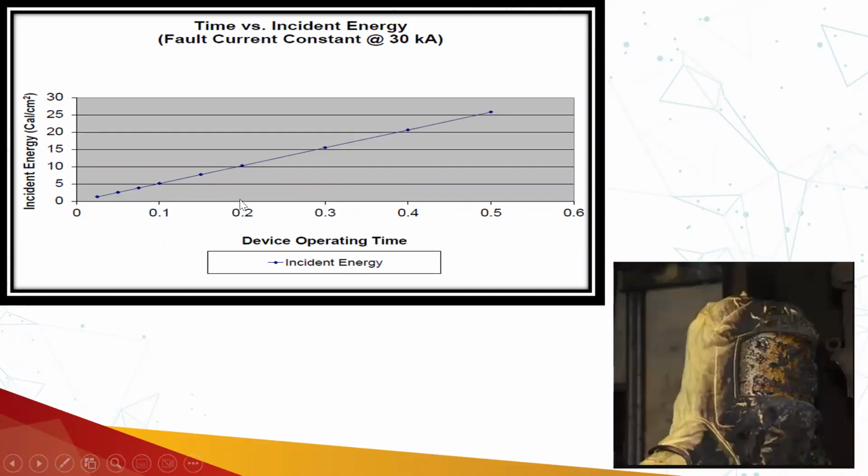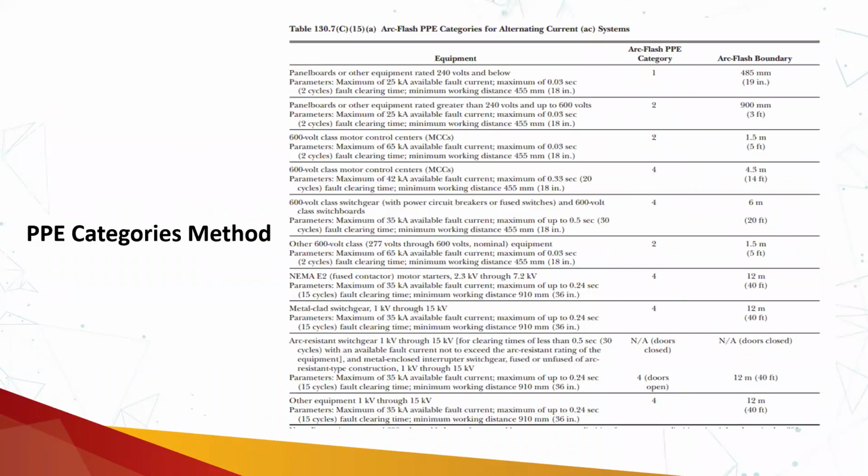So a person wearing personal protective equipment based on the risk assessment performed 5 years back, with the device clearance time increased due to no maintenance, there are chances of fatal or serious incidents in that case. That's why the condition of maintenance is important in NFPA 70E, and it includes a chapter, Chapter 2, related to maintenance as well.